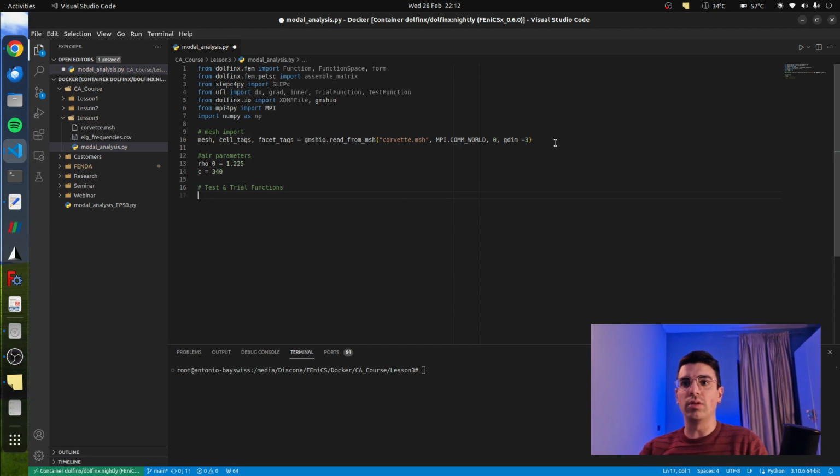So let's set the polynomial degree to 1 for now. Of course, just like I said before, for acoustics and in general, it's way better to coarsen a bit the mesh and then raise the polynomial degree at least to 2. So the accuracy tends to be way better in this way, even if you get, of course, a higher computation time.